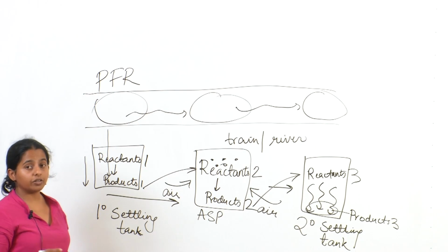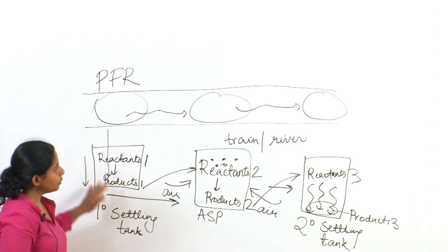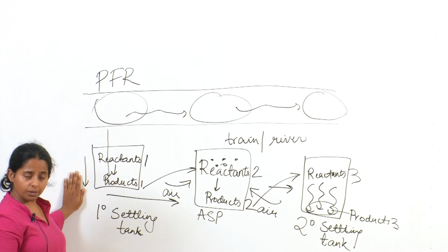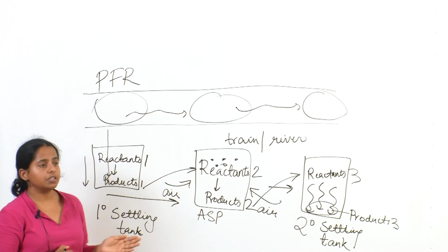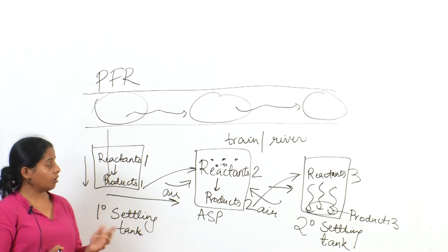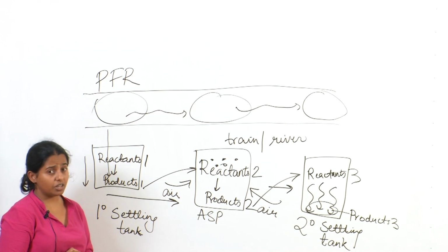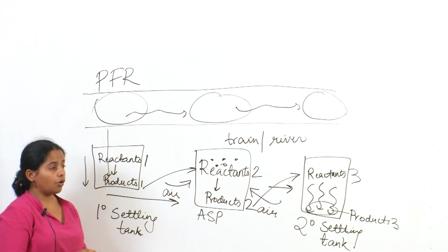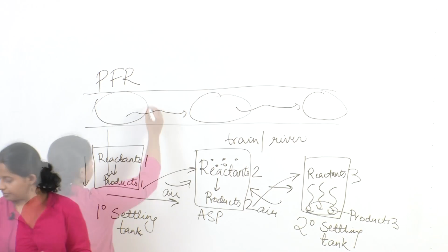Alrighty, now let us go ahead and look at your CSTR based system. I must say that in India initially most of our public water treatment plants were ASP based, but in the past decade we have seen a surge of SBR or CSTR based water treatment plants for the reason that the operation and maintenance is really good and the quality of treated effluent that SBRs are producing is very nice. Also they require less space, and why they require less space, let us look into it.